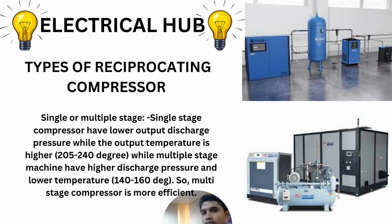Single stage or multiple stage. Single stage compressors have lower output discharge pressure while the output temperature is higher, that is 200 to 240 degrees centigrade. While the multiple stage compressors have higher discharge pressure and lower output temperature, that is 140 to 160 degrees centigrade.